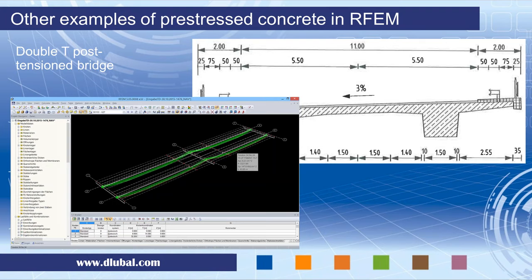The slab had zero stiffness in the longitudinal direction, because there we had the beams, but it has some stiffness in the transverse direction to make sure that those beams share the load applied only on one of them. So that was the model.